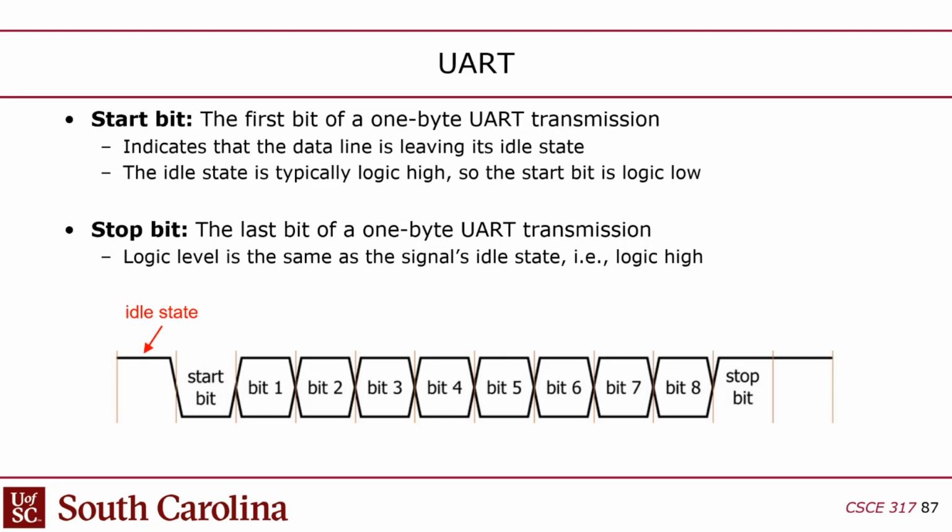So what this means is that there's going to be exactly 1 falling edge of the data in between each 2 consecutive values you send across this thing, right? Because the stop bit is 1, the start bit is 0. So going from the stop bit to the next start bit, you're going to have this falling edge. And this is what it's keying off of. It's looking for a falling edge. If it thinks the bus is idle and it sees a falling edge, it's like, okay, there's something coming across here. That's my start condition. So it looks for this falling edge.